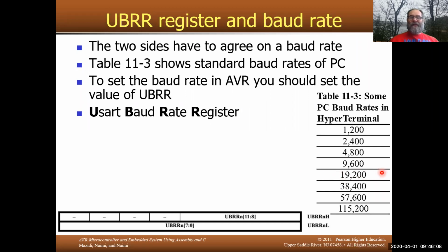Again, that's still incredibly slow compared with typical cable download speeds of, I don't know, anything between 5 and 50 megabits per second. 19.2K doesn't sound that fast, but years ago it was. If you are doing streaming video, high baud rates are pretty important. If you were just sending some status information from one device to a computer, 9600 baud or even 2400 baud is probably fast enough, far faster than it needs to be.